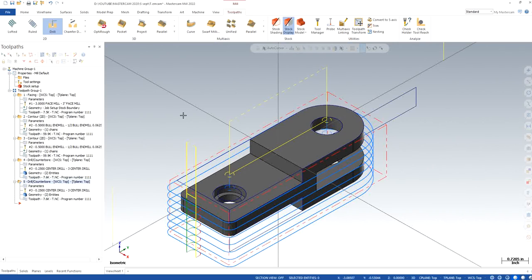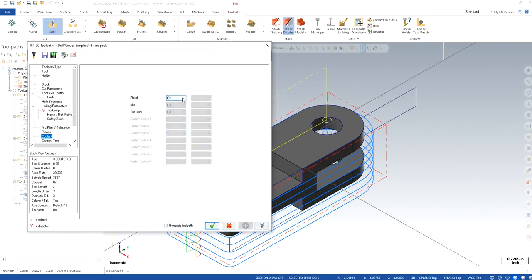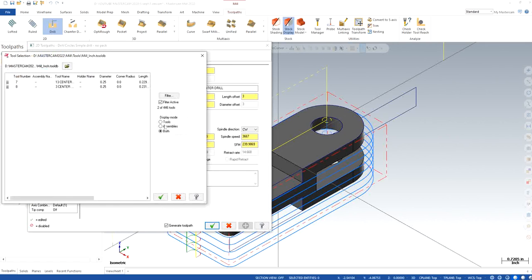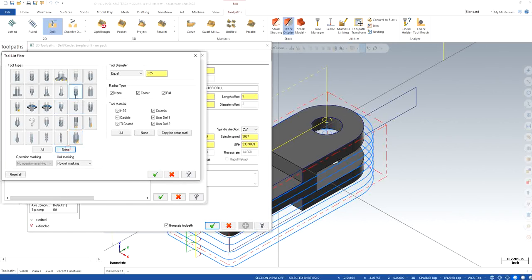So what I'm going to do is just make a pilot drill. I'm going to do the same thing, just change the parameters and the drill size. 0.65 is the smaller one, so I can just look for the drill in particular, 0.65 in diameter or whatever we can get, or I would say between 0.6 and 0.7.